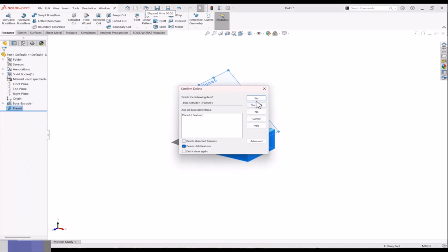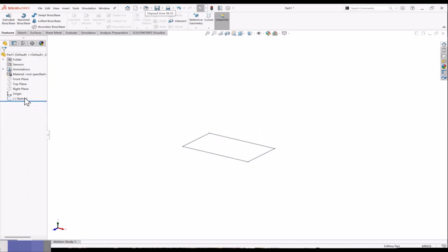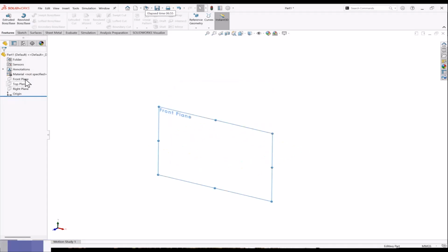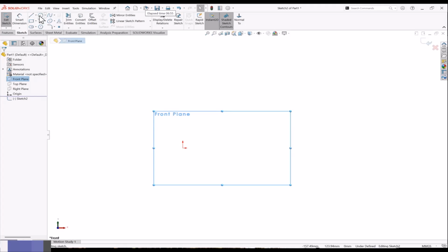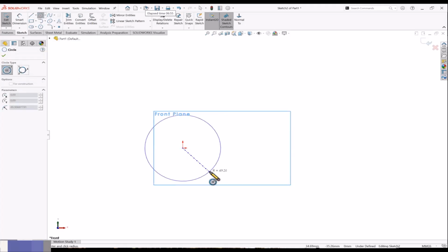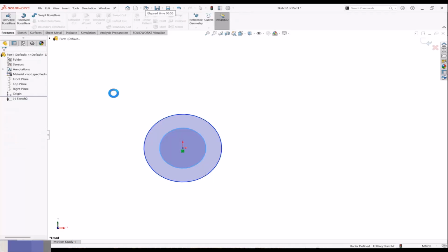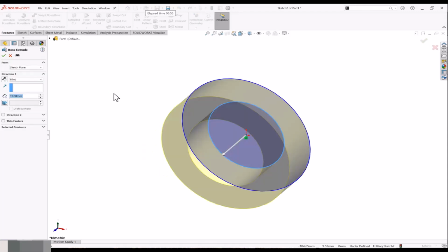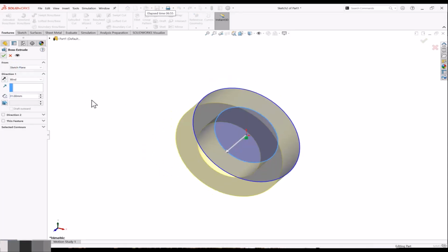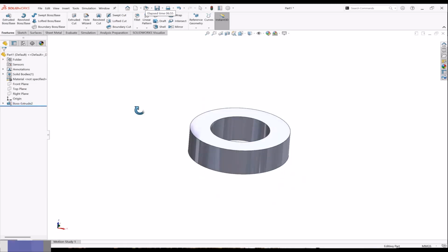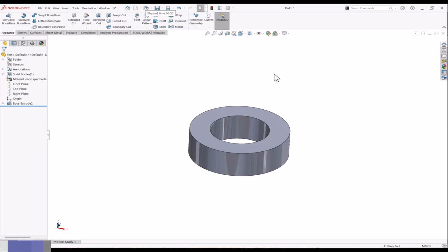If you have some axis, let's create a part in such a way that we have an axis there and we want to make a plane. I'll make a cylindrical object, for example. Sometimes we have a cylindrical case, and if I want to make a plane at an angle, I'll just make one part here and click okay. Now it's a cylindrical portion, right? For the cylindrical portion there's a temporary axis available. You need not create anything extra. You go to the view symbol and just turn on the temporary axis.